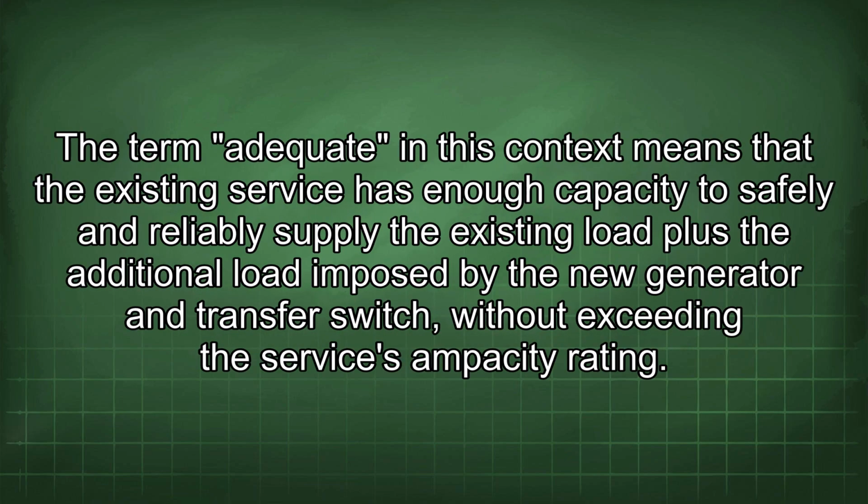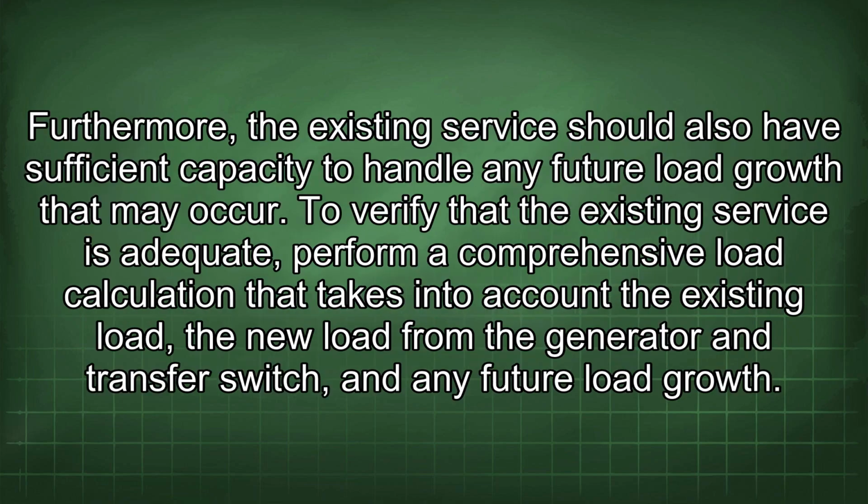The term adequate in this context means that the existing service has enough capacity to safely and reliably supply the existing load plus the additional load imposed by the new generator and transfer switch, without exceeding the service's ampacity rating. Furthermore, the existing service should also have sufficient capacity to handle any future load growth that may occur.